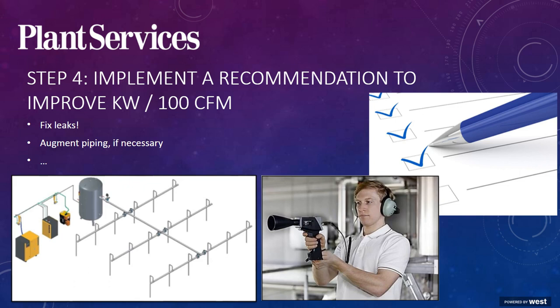So many system assessments are going to focus on reducing compressed air consumption, and what better way to do that than fixing your air leaks? Number 1. We've already talked about piping in our case study example, but there are many times by increasing pipe diameter in the compressor room, distribution network, or to the point of use that can have a huge impact on your overall system operation. And I often say, like simply replacing compressors of one color for another and not changing anything else can lead to repeating the same problems you've already done. So augment piping is a big ticket item right there.